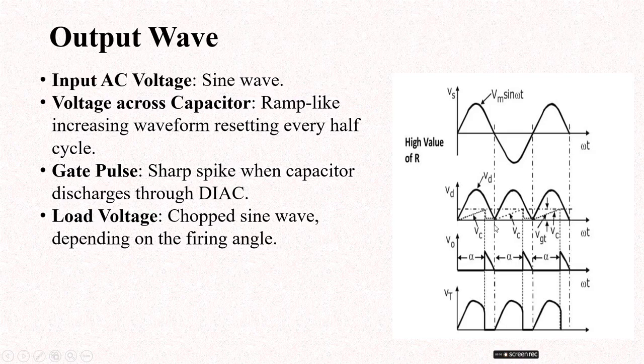Once again the cycle changes, and the capacitor charges and discharges, reaching the VGT value. Observe the graph. When in the blocking state, the thyristor follows the input waveform. Once it is triggered into conduction, the voltage across it drops to zero.